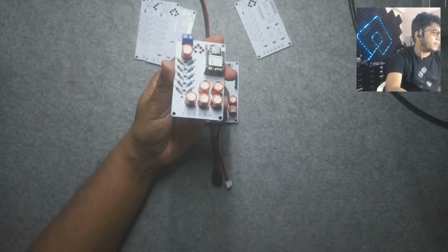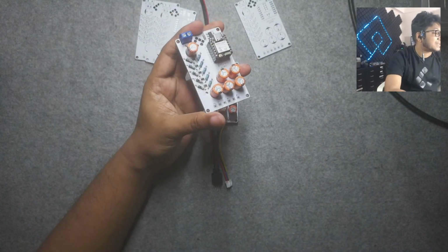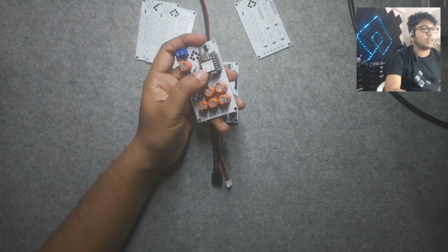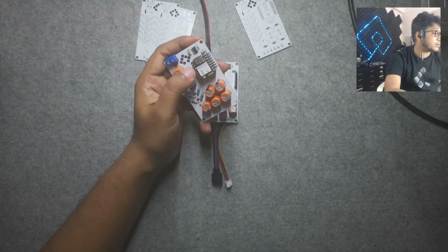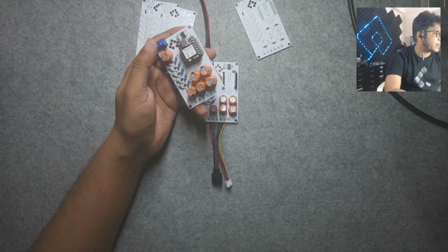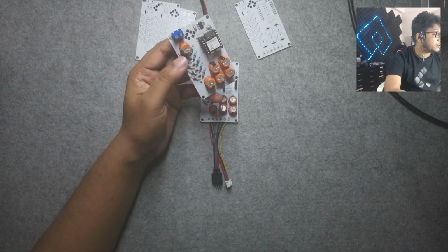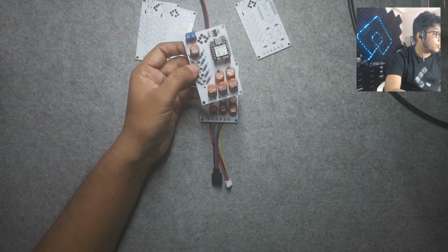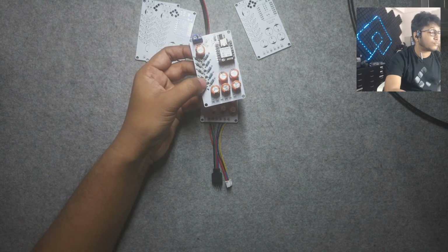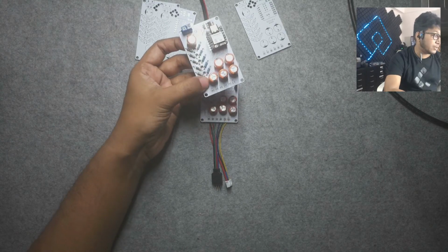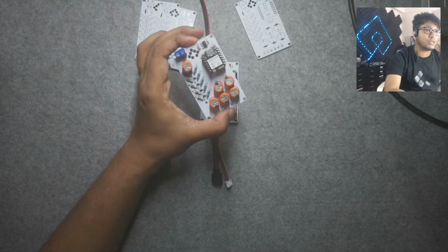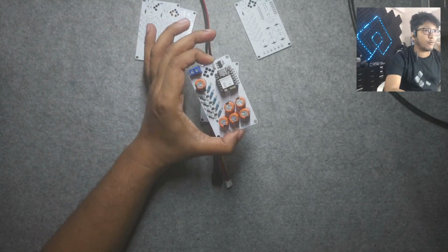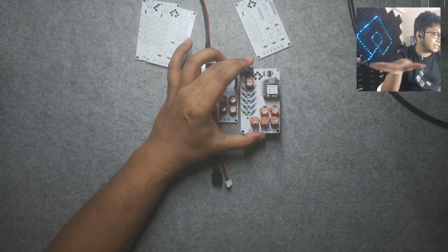If I ever make a more serious or solid version, I might actually end up designing the ESP32 module by myself. It will save space and all, but for the prototype, where I needed to choose parts for the MOSFET that we will PWM for driving the channels, I needed to see exactly how much current they can drive, how much power they can drive, and I'll detail those things.